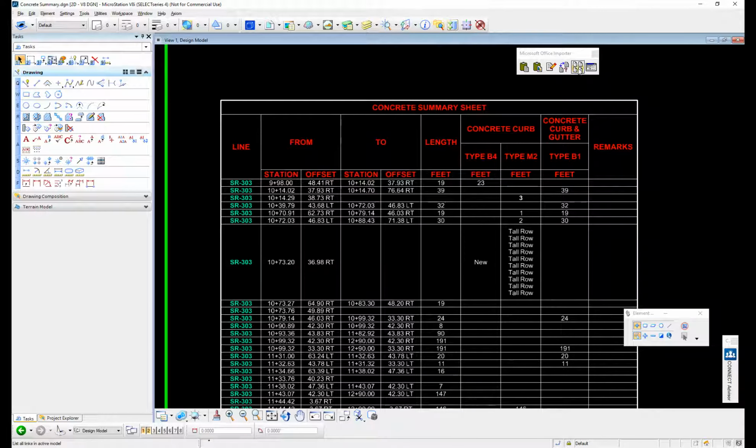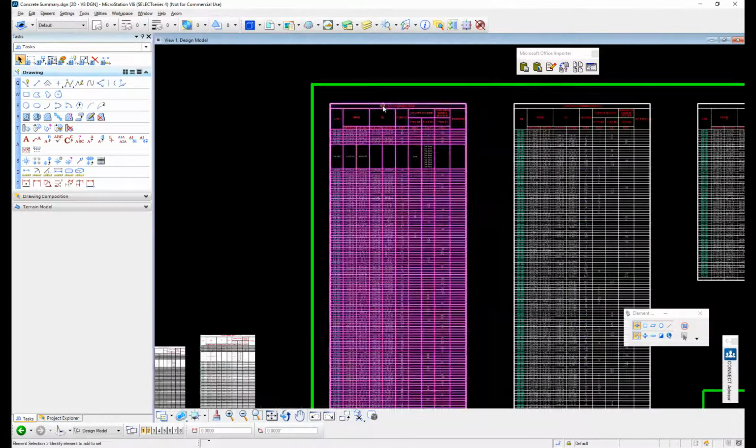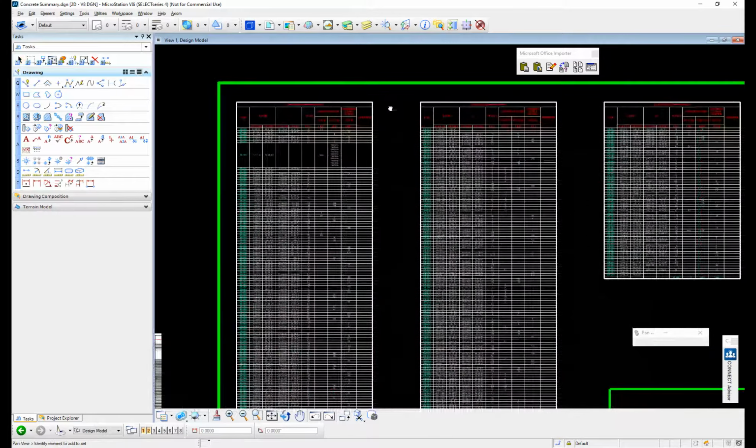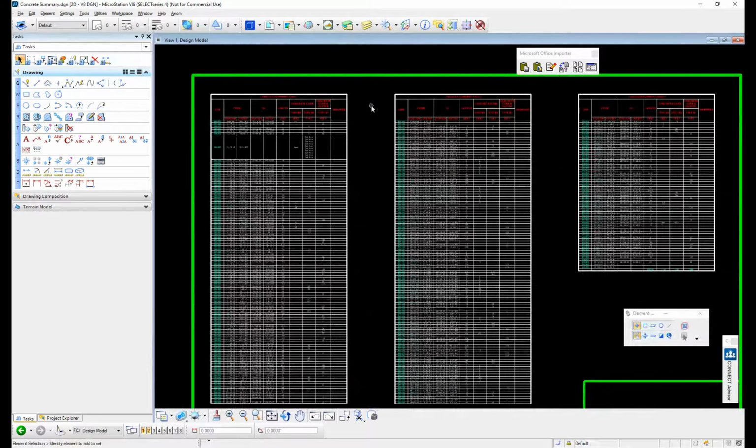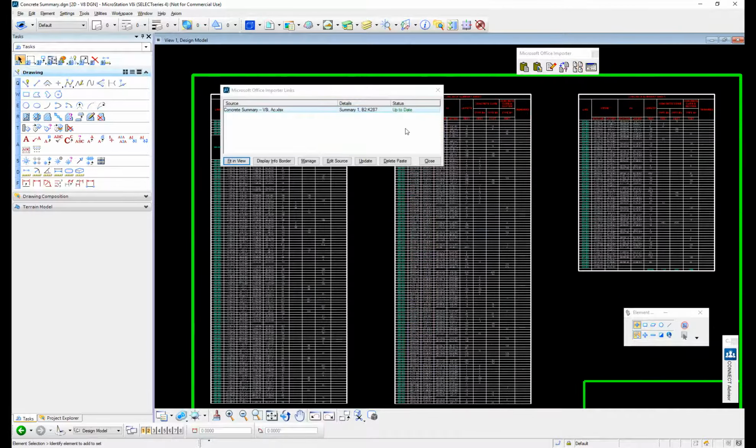But at any time, if you're interested, like say you're pre-submittal or pre-percentage, you're right on the cusp of some percent submittal, and you want to know that the file you're looking at is up to date, you just need that assertion, then just hit this button here, list all links in active model, and we will show you all your imports. Right now, it's just this one. That's usually people have 1 or 2, but I've seen hundreds in one file from guys that are just doing wild stuff. But usually it's 1 or 2, and you can see that it's up to date. So it's in green text, it's up to date.